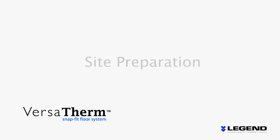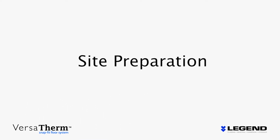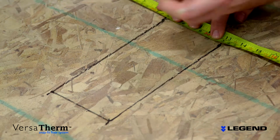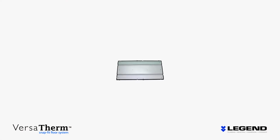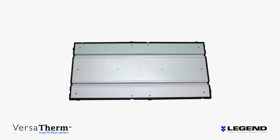The first step is prepping the site. You'll want to communicate with any other trades working on your project. Drywall should be complete, and any future penetrations of the floor for electrical, ventilation, or any other reasons must be clearly marked. The VersaTherm panels have a height of 3/4 of an inch. Keep this in mind when you plan for doors and wall-based molding.